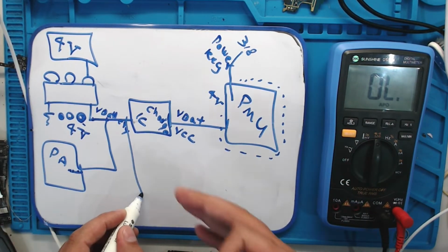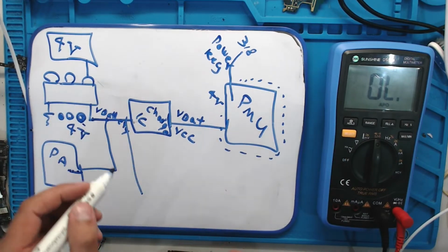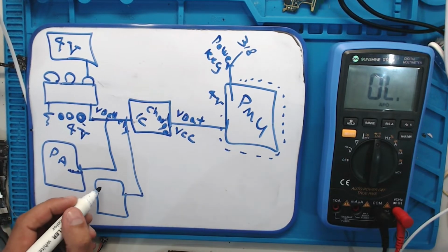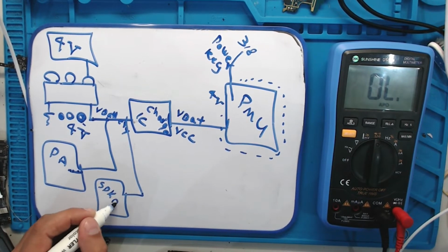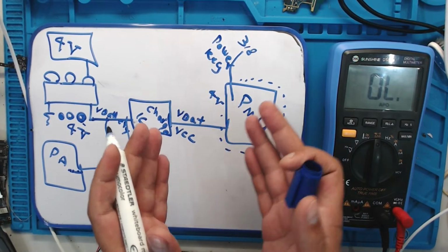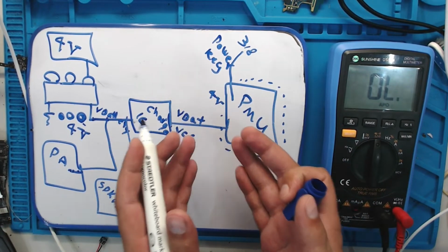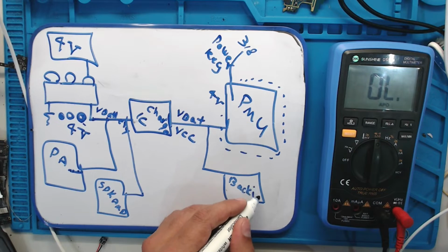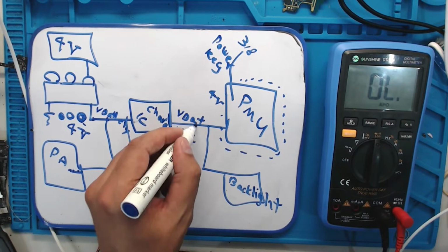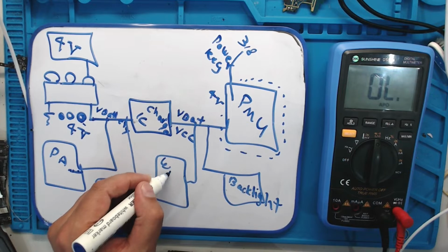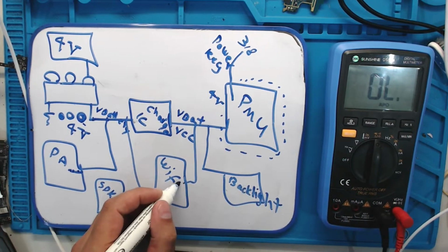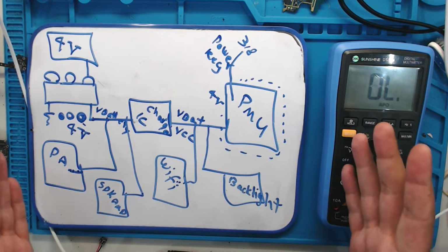From this, again, the first main side delivers main voltage to the other ICs like the speaker amplifier. From that side, the second side comes to the backlight. Suppose it's like this. From it comes to the Wi-Fi IC. Okay, but it is not turned on. This voltage comes inside the IC, but it is not turned on.